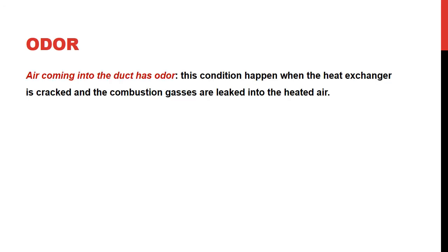If you have odor in the hot air system, which is very common, because again we are heating air, not water, so odor is very alarming. Something is wrong, and it could be the blower fan motor is burnt or burning, or something wrong with the belt, or it could be a problem with the heat exchanger inside the furnace. So if you are breathing combustion gases, that is very dangerous. So take odor seriously, and you have to go and check your heat exchanger using either a smoke test or